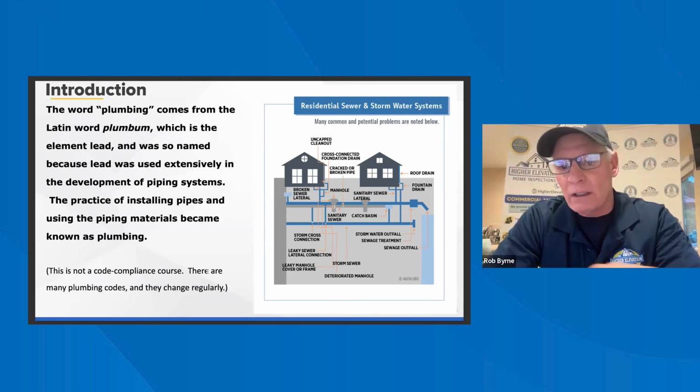Confined space and combustion air. Again, that first video we watched was great. Jim talked about combustion air. If all combustion air is taken from the inside of the dwelling, then you're using up the oxygen in the house. So anytime there are gas appliances, there should be some type of combustion air coming into the space where they are.